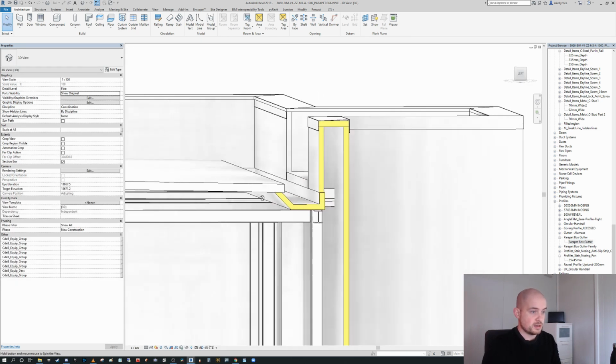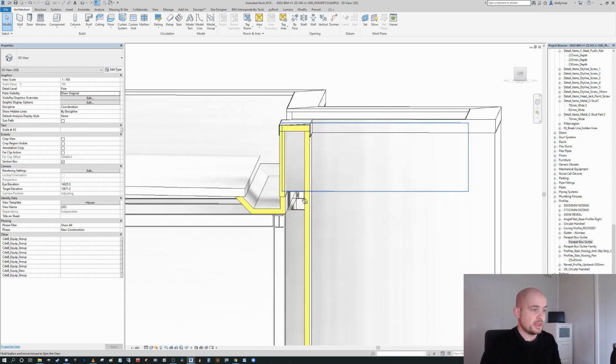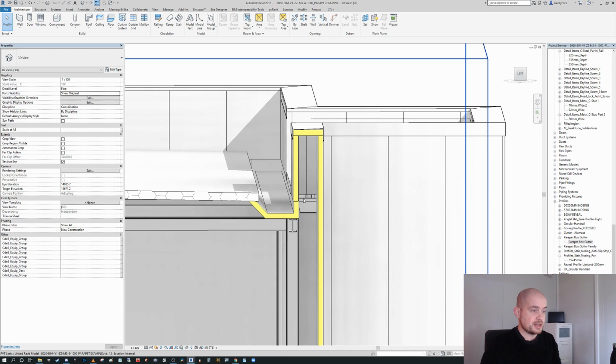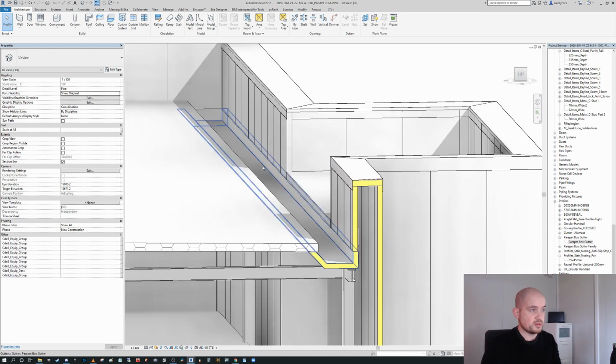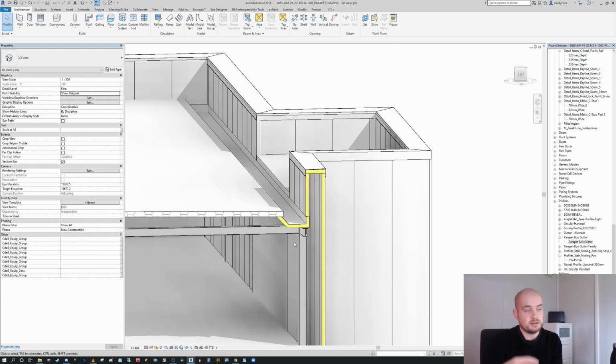Okay, so outside of that, there's just one more thing I want to touch upon very quickly, and that is essentially how to introduce crickets to this. Because the gutter profiles themselves are profiles, they're basically just one shape that's extruded down a path. We cannot use the gutter profile as a way of getting the internal falls within the gutter.